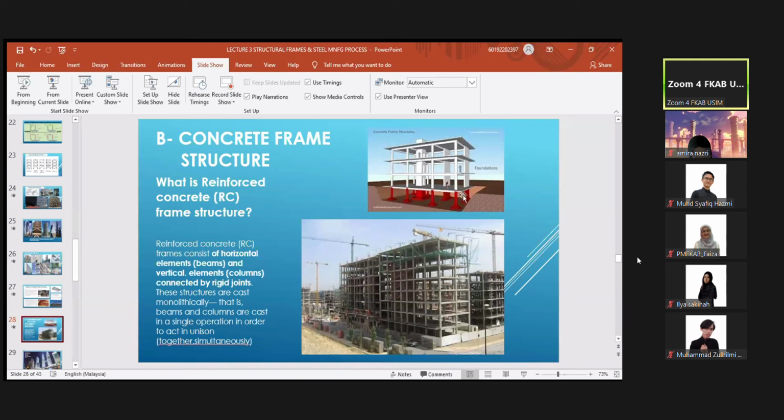Later on, only then you put the floor. Once the beam and the floor are cast at different times, they create what they call a cold joint. That's why concrete has to be rigid, has to be cast together. Once you create a cold joint, some minor cracks will be found between beam and floor slab. This is where the termites come in.